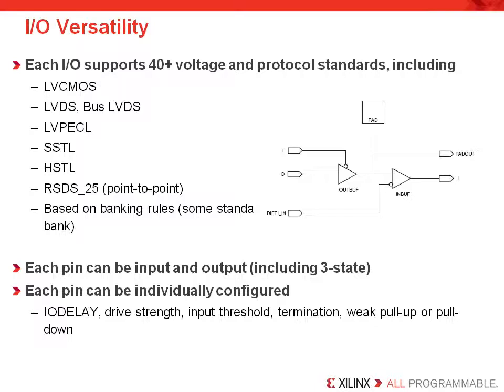Note that there are memory-specific standards of varied classes, and differential standards that require 2 I/O pins to receive the signal. The differential signaling standards include LVDS and LVPECL. The single-ended I/O standards include LVCMOS, SSTL, and HSTL. The SelectIO feature allows direct connection of the FPGA pin to external signals of varied voltages and thresholds. This optimizes the speed-noise trade-off and saves you from having to place interface components onto your board. All of the dedicated interface logic already exists and can be selected on a pin-by-pin basis.